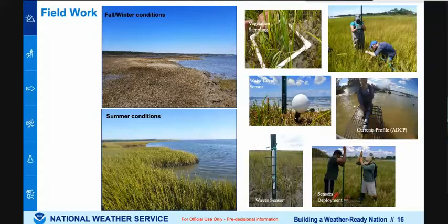And since we had wave gauges and also water level gauges at the same locations on those transects, we could run the ADCIRC model, validate the ADCIRC model, and also we ran the WaveWatch 3 model and compared the results at those gauges, and we had some very good results based on our study.